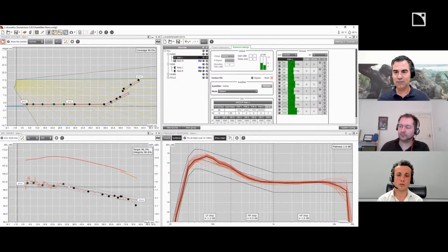So for those of you who don't know what standard deviation is, it evaluates the tonal variation on these 3 frequency ranges. The first one being up to 200 hertz, then between 200 hertz and around 1 kilohertz, and then up to 10 kilohertz. For each frequency range, we try to evaluate the variation around the mean value. So we're not interested in the absolute level difference. We want to remove that and just check if the tonal variation, the sonic signature, is the same. And in this case, it's pretty impressive. Got it.